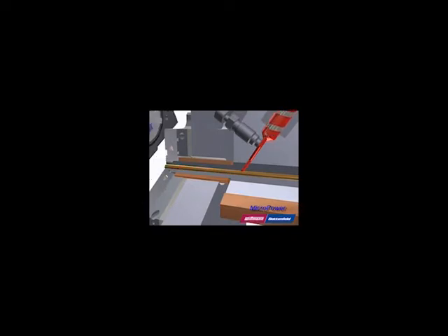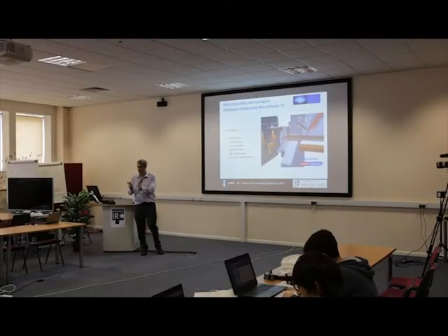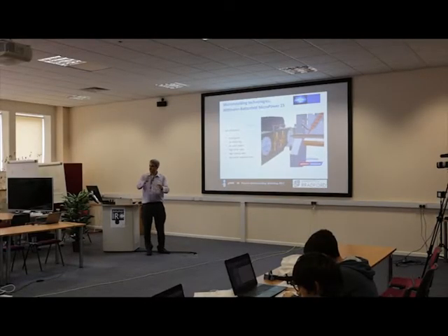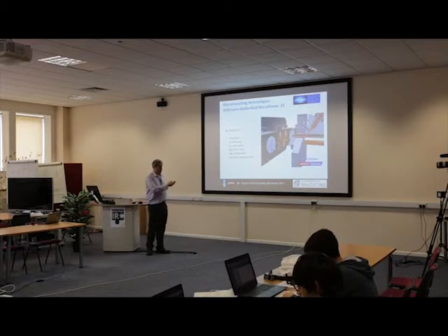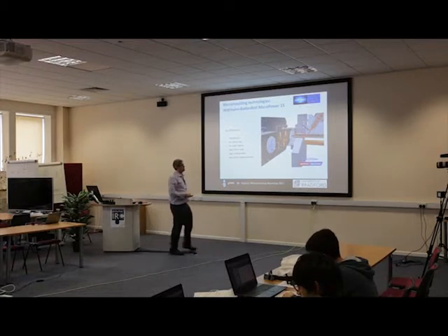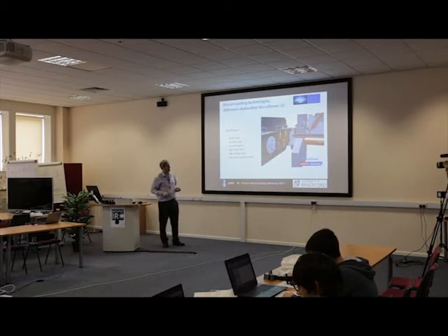Because basically all our material is going into the cavity, so we don't leave any melt left in the screw, unlike conventional injection molding where we have this melt cushion material, which is going to then go into the next shot. With this one, the entire shot is distributed into the cavity. We don't have any sprue material, so we're minimizing the amount of material that we need to use. And we've got a nice separation between the cold mold and the hot material preparation area as well.